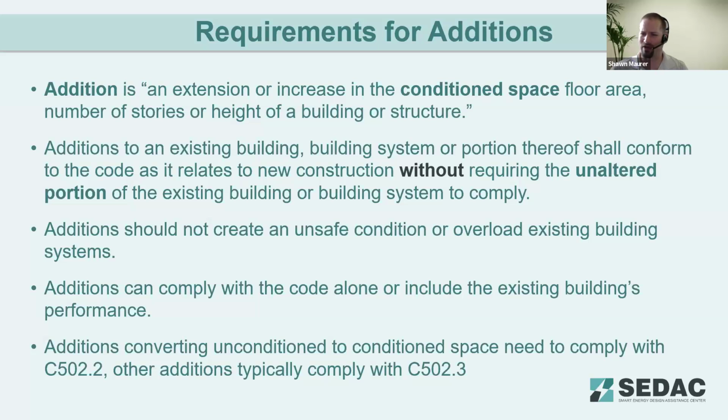An important part about additions is they can't create an unsafe condition. So if you're adding a floor to a building, it can't structurally overload the building. If you're adding in conditioned space, it can't overload the existing HVAC systems. It would need to have its own standalone HVAC system. So that's an important part about performing an addition to a building.